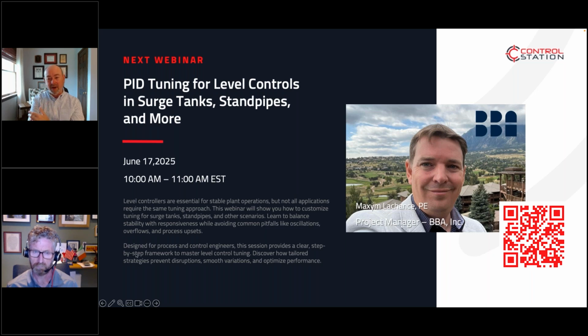Make sure I've thought about corrosion resistance. Is it worth a little more money for a more expensive, more corrosion-resistant metal to avoid a stiction problem down the road? Those kinds of considerations are key in the upfront design of the plant, or in the selection of a replacement valve, if you should get to that point.